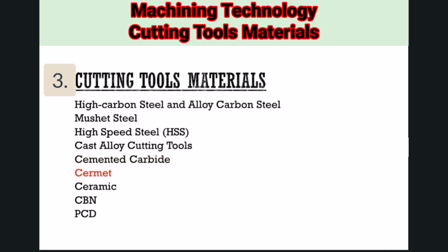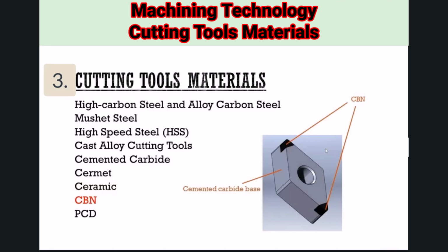Cermet is very similar to cemented carbide. However, it includes some titanium hard particles. Cermet tools are very wear resistant, and it is possible to get a very good and shiny surface finish with them. On the other hand, they cannot withstand high compressive stresses, so the recommended cutting depth and feed for them is low. Cutting tools made of ceramics are mainly used to machine materials that create excessive wear or heat. There are ceramic tools specifically made to machine hardened steel, cast iron, or heat-resistant superalloys.